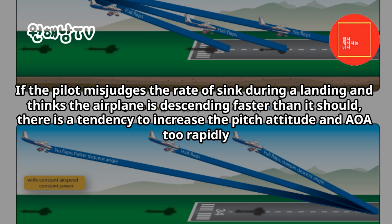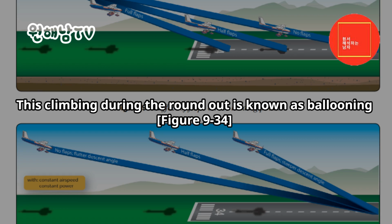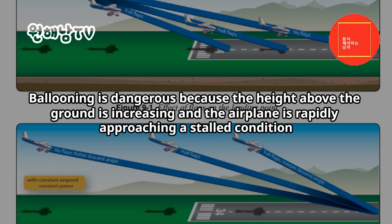Ballooning during round out. If the pilot misjudges the rate of sink during a landing and thinks the airplane is descending faster than it should, there is a tendency to increase the pitch attitude and AOA too rapidly. This not only stops the descent, but actually starts the airplane climbing. This climbing during the round out is known as ballooning. Figure 9-34. Ballooning is dangerous because the height above the ground is increasing and the airplane is rapidly approaching a stalled condition.